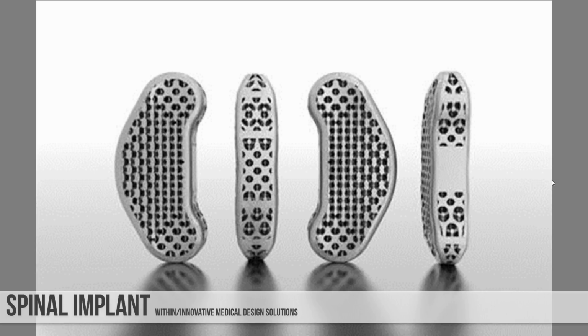All right, this is a spinal implant. It has the same sort of mesh or a similar mesh. This is inserted. It's basically a disc replacement for the spine. This is from a company called Innovative Medical Design Solutions, and it was designed with a software called Within. So I mentioned some software that is kind of specialized at creating cellular structures. The software called Within is one of those. So the designer basically creates the outside shape, and the follow-up software creates the cellular structure. So that's all done mathematically. The engineer doesn't have to worry about doing that.